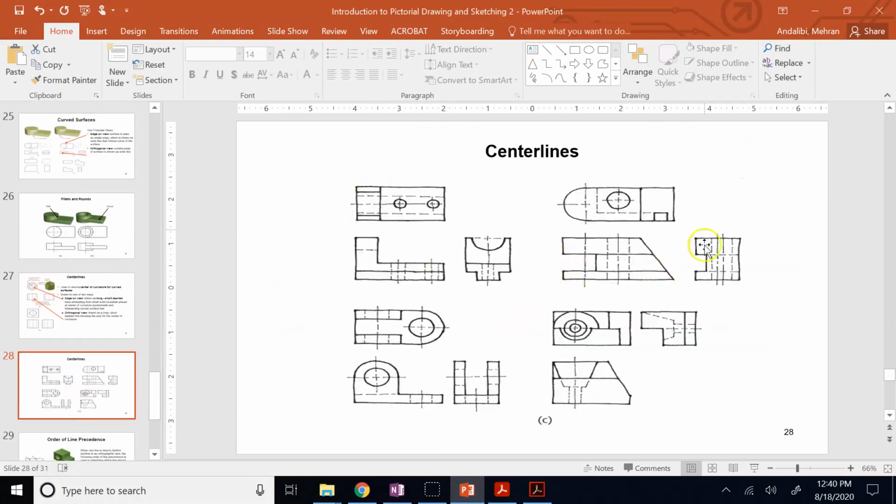Okay, so here you can see different center lines for different cylindrical surfaces. One other thing you have to pay attention to is the half cylinders. If you have half a cylinder, then you do not have those infinitely many planes of symmetry. You have half of them.